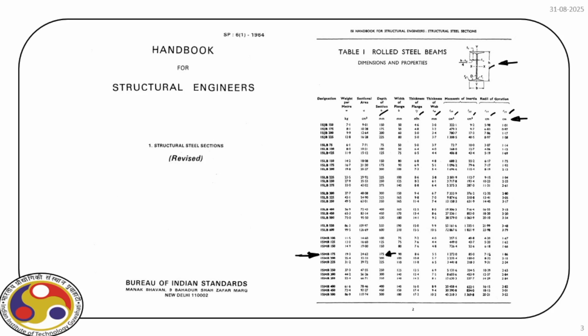So what we'll do, we'll read this line, and from this line, we'll get all the properties of the section that is required. Otherwise, we need to evaluate the moment of inertia, cross-sectional property, and all other, say, the Q that we are going to find out today. For that, again, we have to split this because this is an I section.